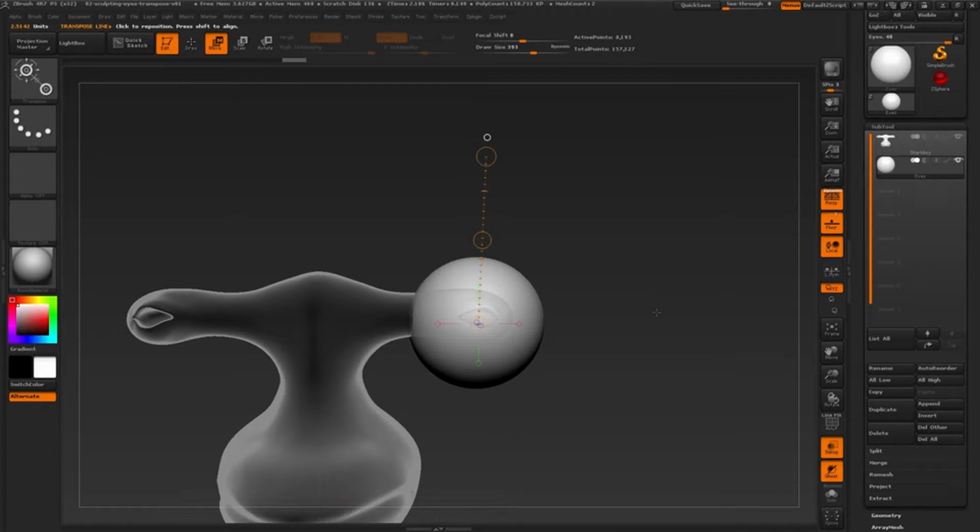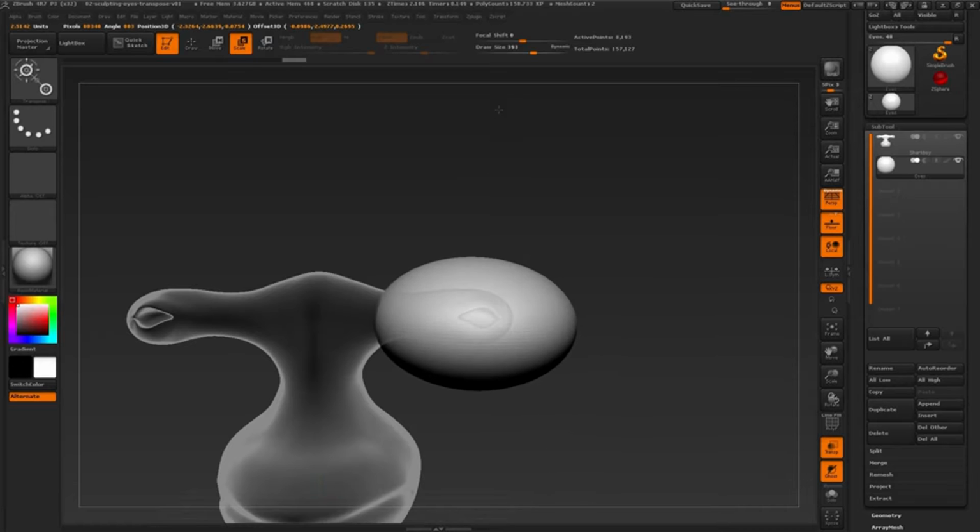To scale the eyeball, let's switch to our Scale Transpose option. This action line will always look the same, but now our three primary action line circle options will apply different scale options to the mesh. In the case of transpose with scale, if we click and drag from the center circle, this will actually deform the mesh, which is not what we want. We want to keep this as a perfect spherical shape for the eyeball for now, so I'll press Ctrl Z